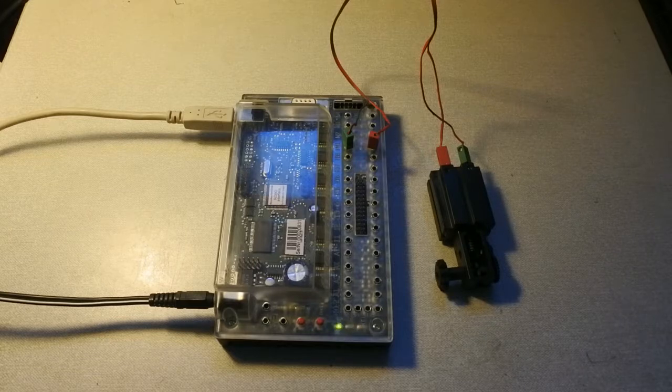The interpreter is loaded in one flash memory. However, since the second flash memory has a limited number of writing cycles available, it is very much recommended to load any program that you want to run into the random access memory. So power off means gone.